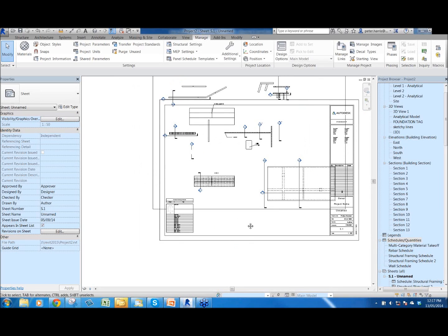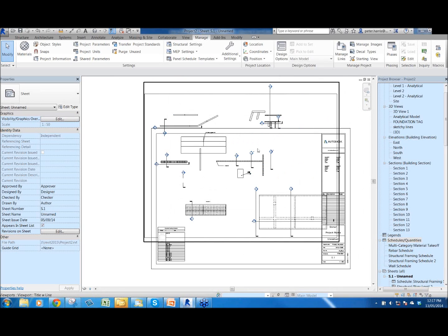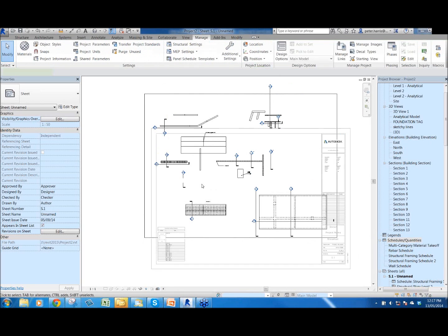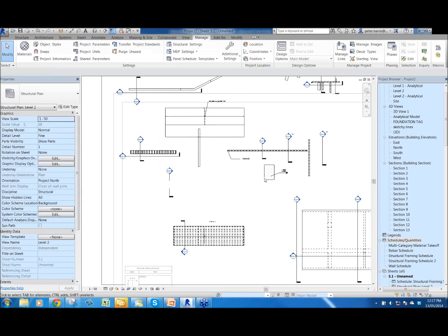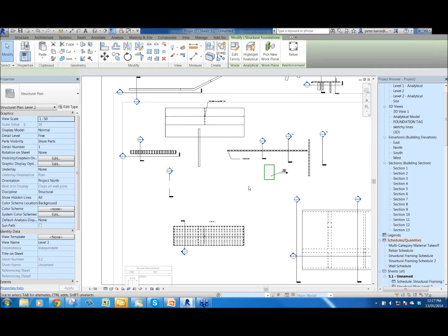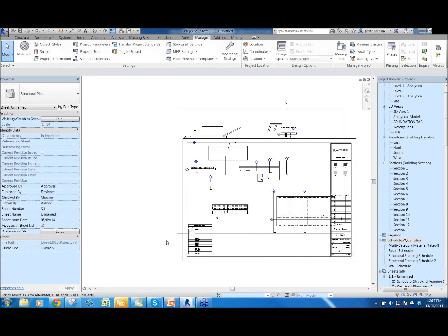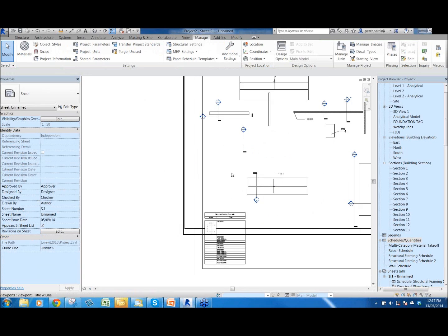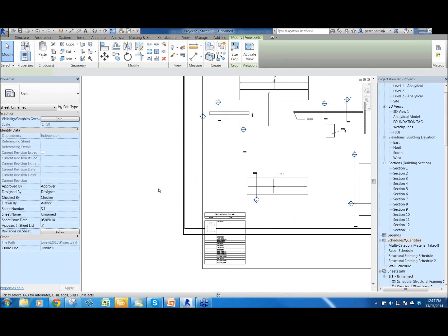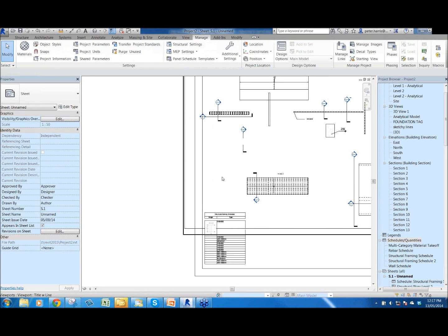Some of the view options. So in the past, 2014, we could always double click a view and that would have activated a view. So in AutoCAD days, working inside the viewport, this allows us to modify whatever we need to do. In the past, we've always had to right click to activate view. Now we can double click on the out and it deactivates the view. So it's double clicking in, double clicking out. Again, little things, but little things often save some time.